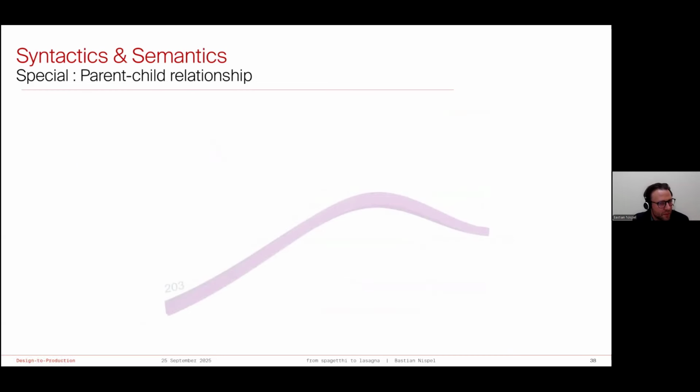Yeah, last one before we jump into the showcase is about parent-child relationship. So let's say you created, in a reference model stage, in a coordination stage, whatever, a beam which is continuous over the whole surface, following a reference axis, and now you want to make segments out of it. Then we can say, okay, this is a parent. We want to keep it. We don't want to get rid of the information we already created. We want to put new information on top of it.